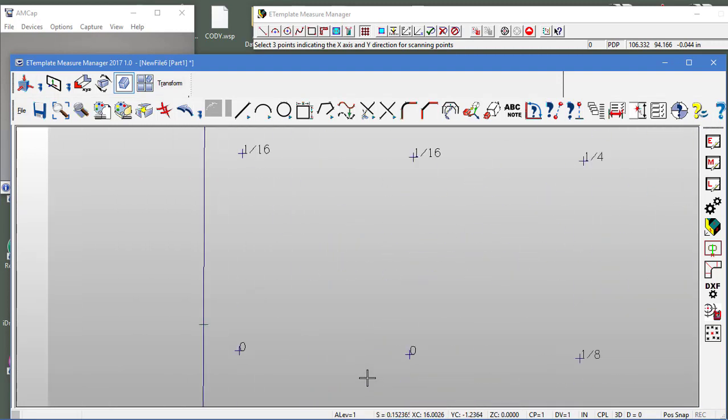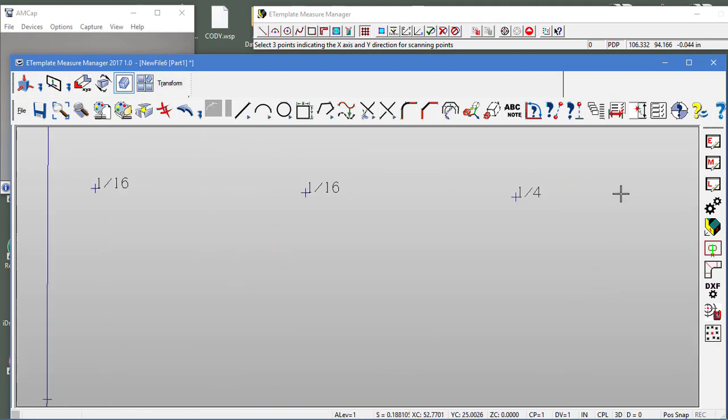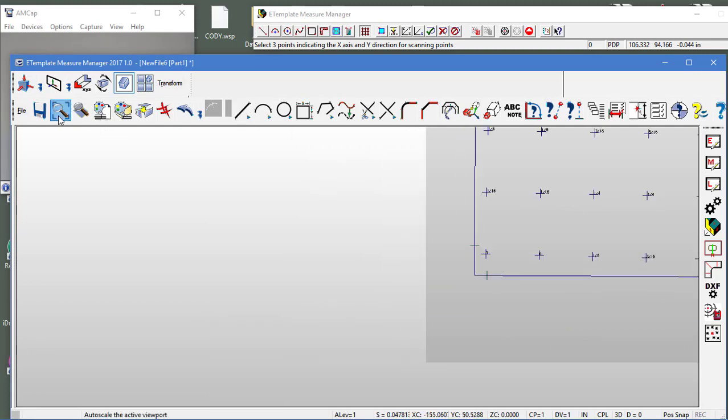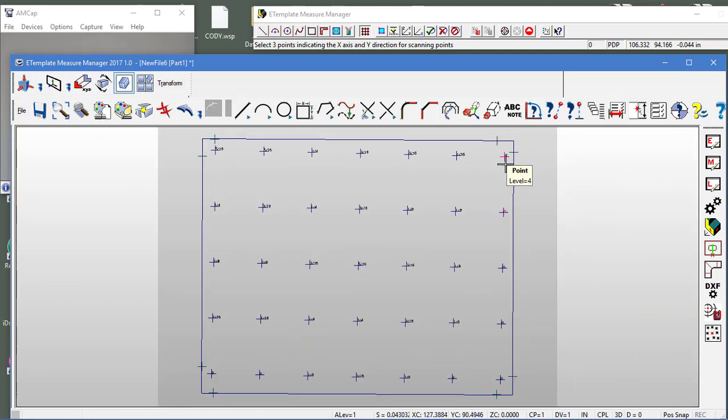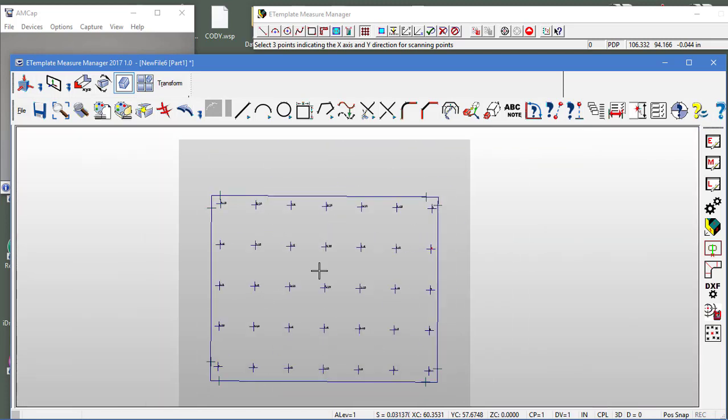And again, looking over here, you can see this isn't too bad a wall, but it does have some movement in it. So if I wanted to create a fascia on here that was perfectly level, I don't need any inserts or spacers here, or I need a common amount of space there. And then I need more spacer, and more spacer, and more spacer to flatten up this front surface if I wanted to make it perfectly vertical. So that's one way of analyzing just a wall and taking a look at how much you'd have to shim it to put a fascia on that would be perfectly vertical.